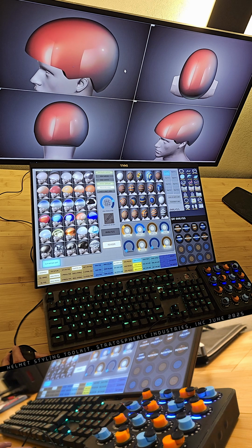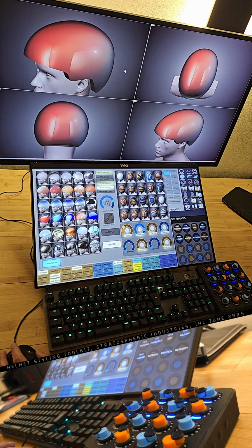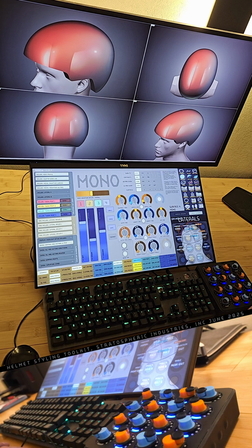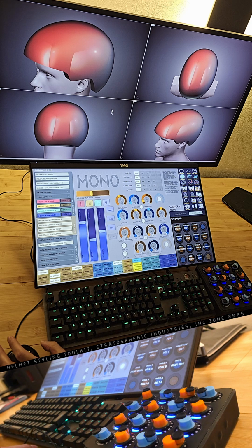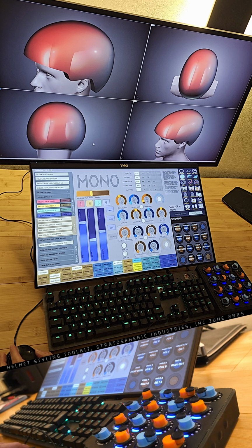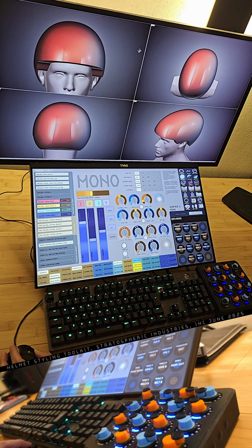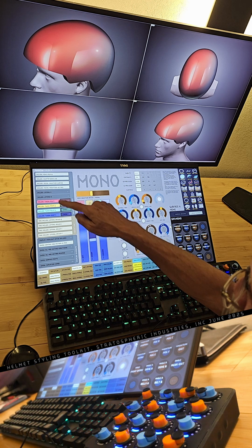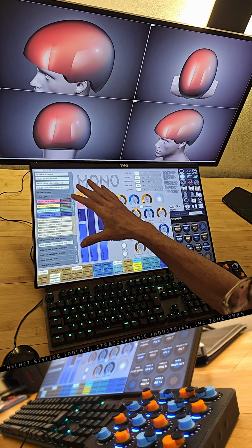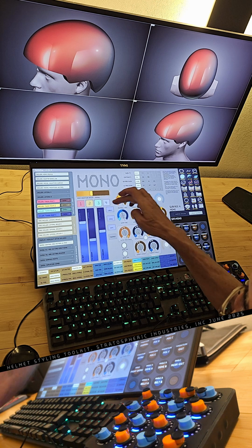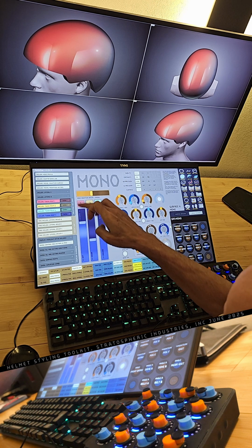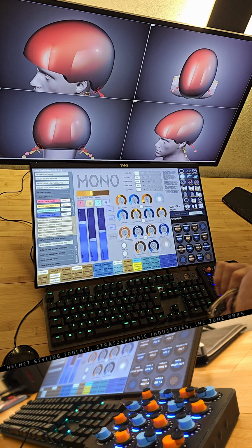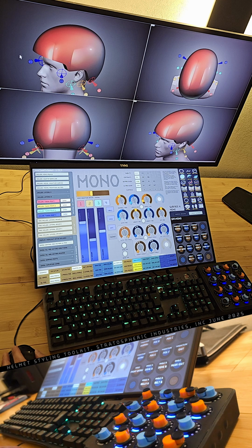Now, let's keep this right here as our working model, and let's examine the method for tweaking this surface. There's a lot of tweaks you might want to get full control over this surface. This is quite a rounded look, but let's say we want to have a little bit square in one area. So there are a whole series of tweak points. This is for each of the surfaces. There are 4 tweak points currently that can be controlled. This controls the display of the tweak point. So let me turn those on. They are now all starting lower on the helmet.